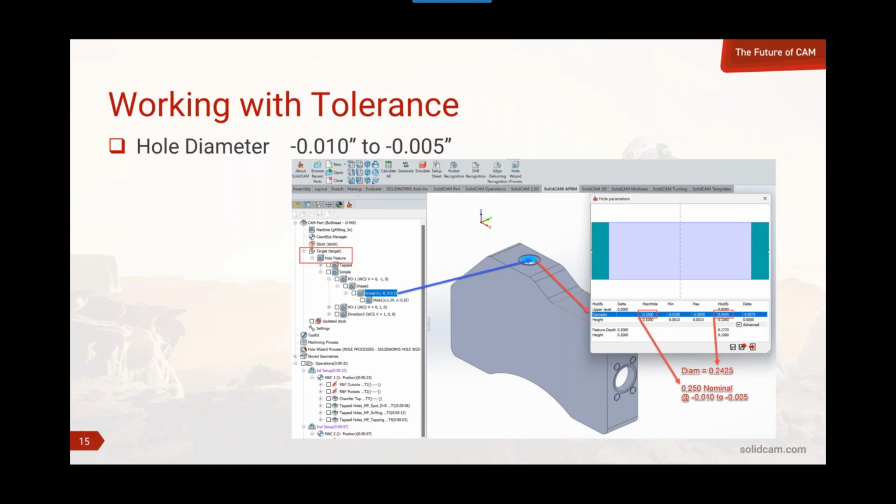And then at that group level, we have access to not only the actual nominal hole size from the CAD feature, but we also have access to min-max tolerancing. Now, right now, this is manual. We are working on capturing this data from Dimension Expert and from the STEP 242, what they call PMI data, the Product Manufacturing Information data, okay?